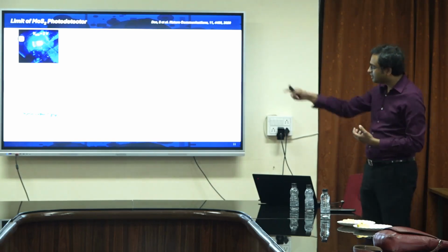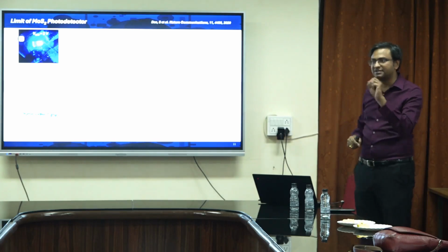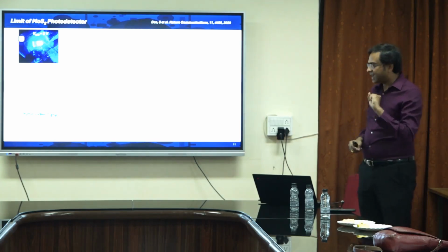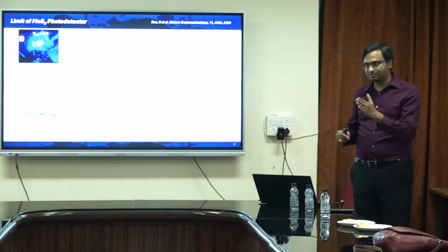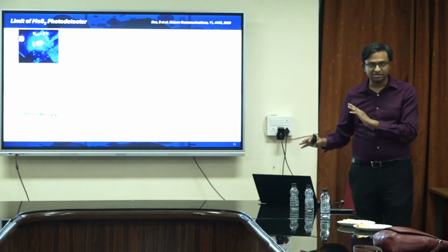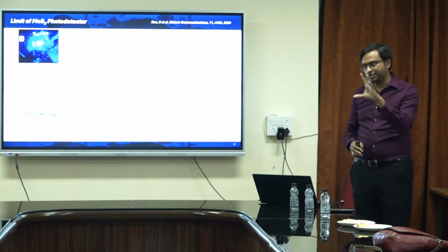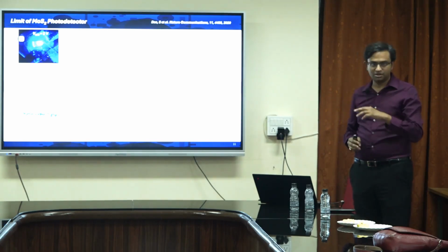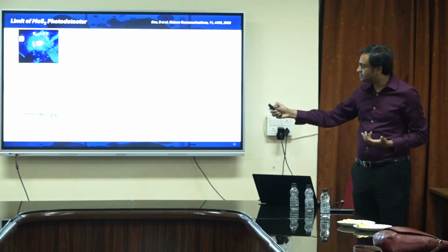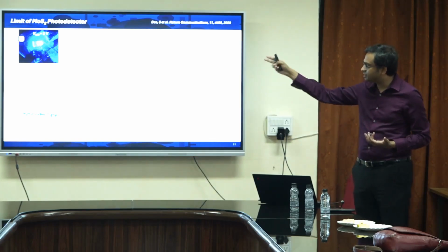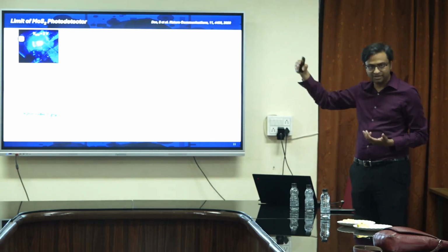If it's a bright light, what I am doing over here is simply pulsing the light at a certain frequency. So when I measure the photocurrent response and take a fast Fourier transform, I will get the frequency at which the light is giving me the signal, right? And you can see that I get that signal because the LED is turning on, off, on, off, on, off, on, off at a certain frequency.